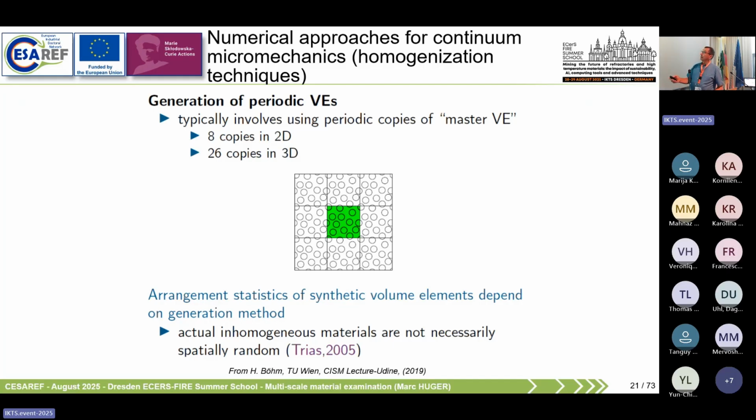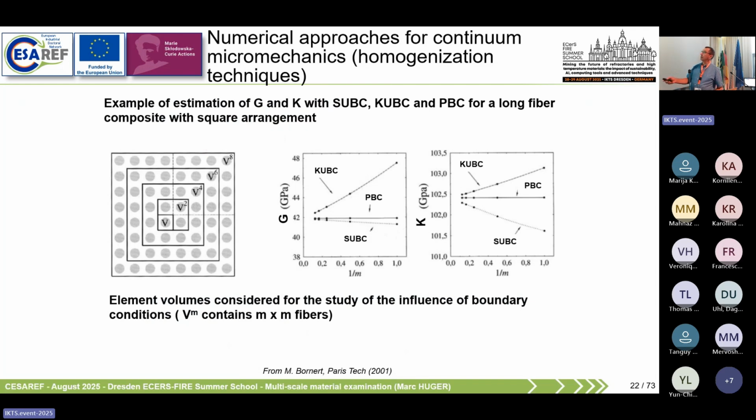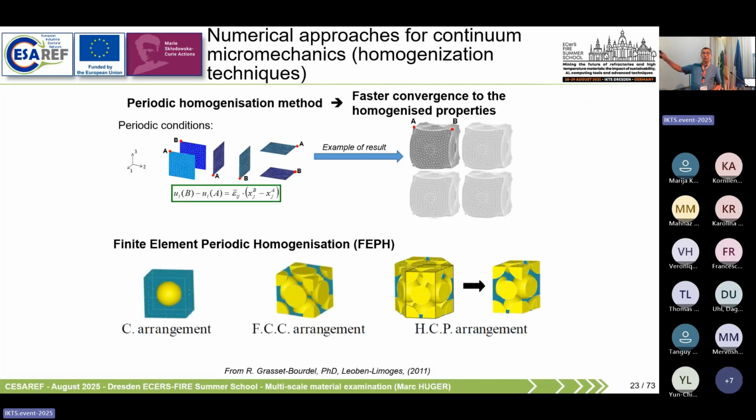The periodic boundary condition is a key point in order to describe the property, because if you really use periodic boundary conditions in modeling, you are able to describe a quite large system, even with a very small amount of inclusion, because it works with only one single bead. It can describe your system perfectly in that case. And this is quite simple, I would say, in modeling. We can do that also in DEM, but this is well known in FEM modeling.